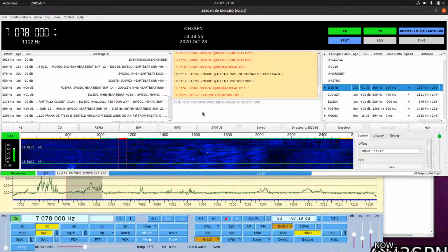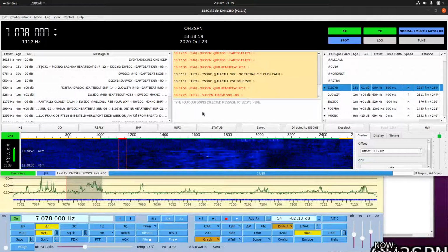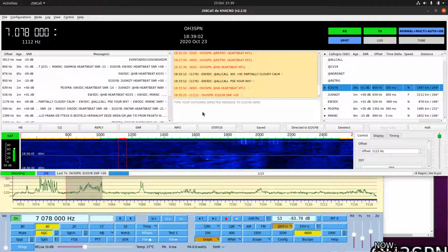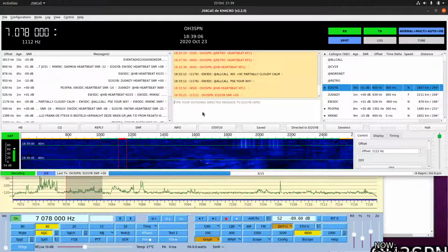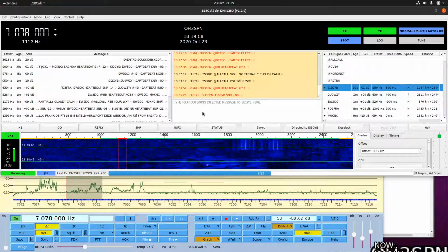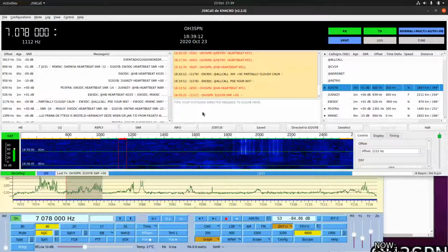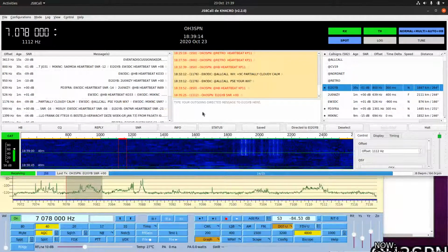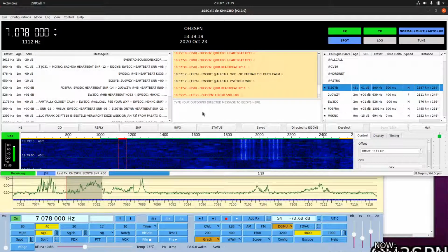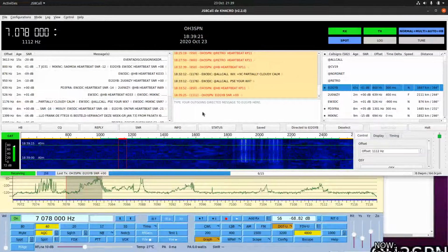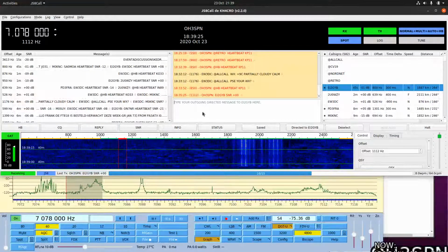It's no good saying you're S5 against some imaginary receiver noise floor, which is never going to mean anything. But I'm just moaning now. The receiver noise floor is much lower than you'd realistically ever experience. So the S reading is a bit irrelevant unless you adjust it against something, which normally should be your noise floor.